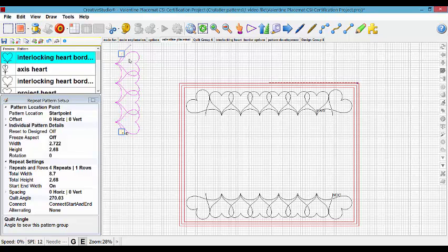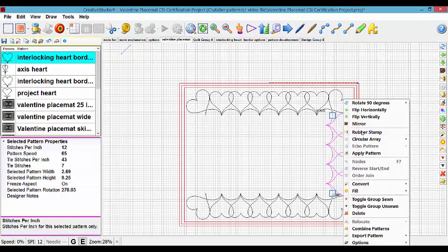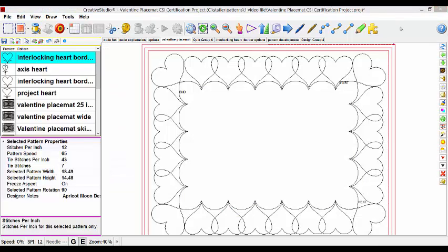The blue anchors were the last that we used, and so they have remained. We're going to cycle those to the purple anchors, bring our pieces down, cycle to the blue anchors again, and snap the pieces into position between the corners. Again, we will use rubber stamp, then use the copy for our left border, placing using the blue endpoint anchors. Select your border, right-click, rubber stamp, press Escape, select your endpoints, and snap into position. When all four borders have been placed and endpoint snapped, it's time to set the stitching order.